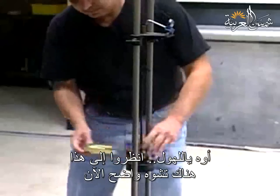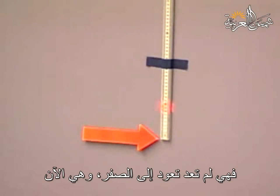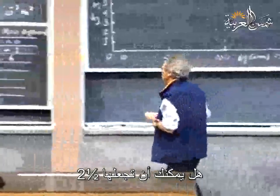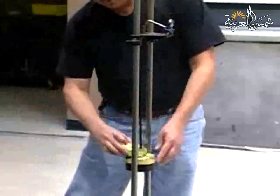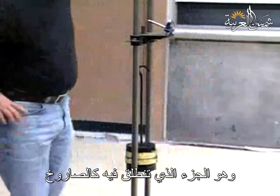Oh boy, look at that. There's clear deformation now. It no longer returns to 0, and it's comfortably 10 centimeters long now. So can you make it 2.5? You're now slowly approaching the part that I hope you were going to see, and that is that it's going to take off like a rocket.